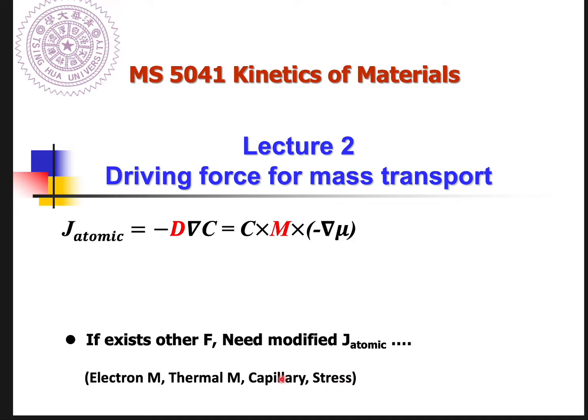And we are going to talk about the capillarity and stress effects. These two driving forces: what's capillarity? If your material is not flat, with different curvatures existing on your materials, we need to modify the chemical potential of the atom at the curved surface, right? That will result in a variation of chemical potential.